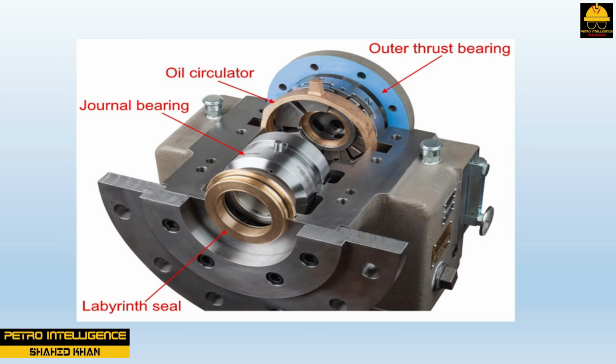Bearings. Bearings, as shown in the picture, provide radial and axial support for the shaft of a steam turbine. Radial bearings, also called journal bearings, are designed to keep the rotor of a steam turbine from moving from side to side or up and down. Oil supply passages are built into the radial housing, or a slinger ring lubricates the bearings. As the shaft rotates, the lubrication forms a thin film between the shaft and the bearing that allows the system to float. This type of bearing typically is located beside the thrust bearing on one end of the turbine and by the shaft seal on the other.